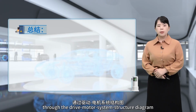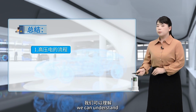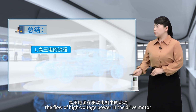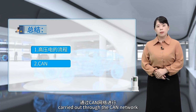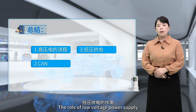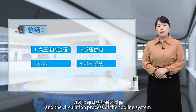Next, we will learn about the relationships between the various components through the drive motor system structure diagram. From that diagram, we can understand the flow of high voltage power in the drive motor and data exchange between the components carried out through the CAN network, the role of low voltage power supply, and the circulation process of the cooling system.